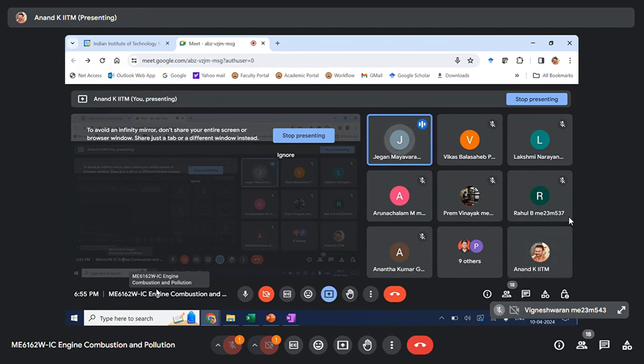Understood. So in this case, the exhaust gas which comes out has more hydrocarbon, and we have more air also. So we can use this for EGR, exhaust gas recirculation, so that we can enrich the mixture for my next cycle. EGR composition is highly variable compared to an SI engine. Here you have oxygen in the EGR. Okay, sir, because we have hydrocarbons as well as oxygen here? Yes, in a good proportion.